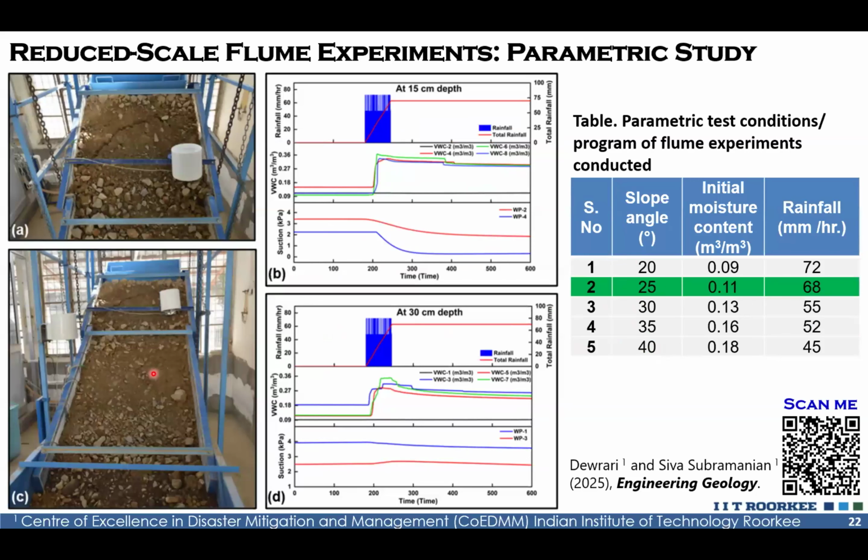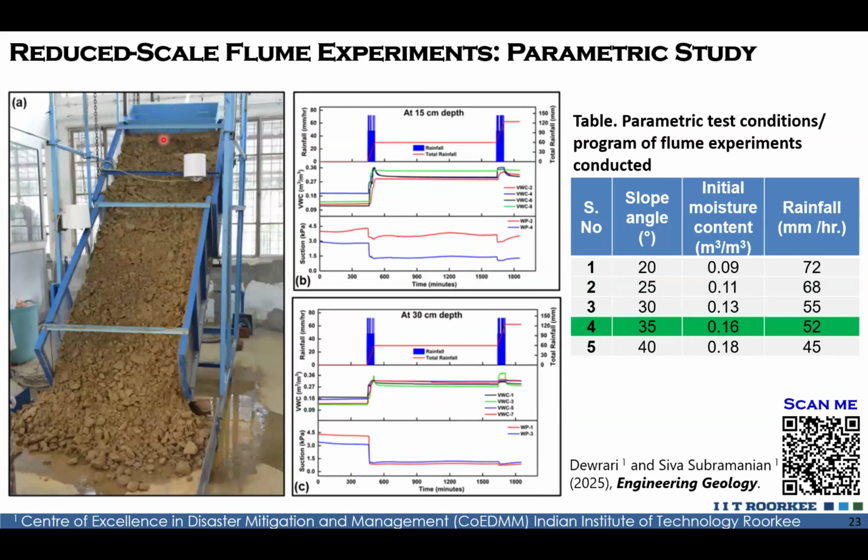Here you can see the first test. A tension crack developed at a certain time after the rainfall was supplied, whereas there was no failure except for some amount of material at the toe. In this experiment, we have a slope failure at the toe part. We believe this is what we see in the Himalayas when we approach the road and make the road excavation: the toe part gets destabilized, wherever the material is a soil-rock mixture, that is, a mixture of rock fragments and fine soil.